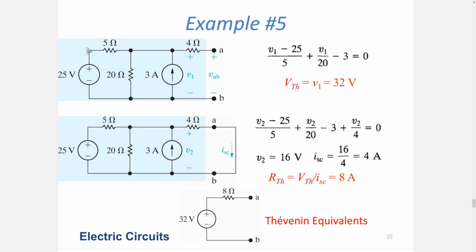We have the 2 nodes here, because there is no return path for the current to flow. So it's just dangling. It just acts like a wire. As long as there's no current flow, I can measure the voltage. This resistor has no effect because the voltage cannot drop over it. The current is 0.